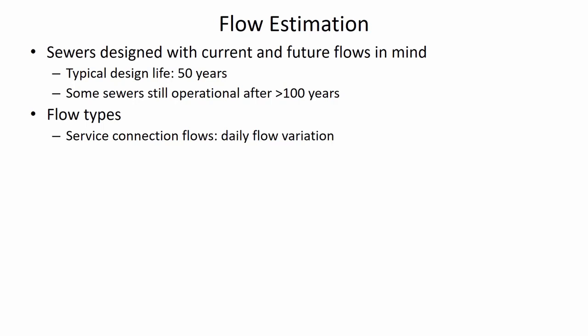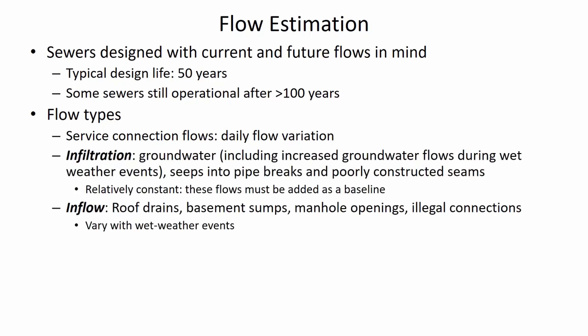So there's also a similar variation in when the water is going through sewer pipes. And so they have big peaks down at the sewer plant at night during the same times that people are using water for washing clothes, flushing toilets, taking showers, and so on. So there's a lot of daily flow variation. And the pipes have to be designed for the peak hour in the peak design condition some many years in the future.